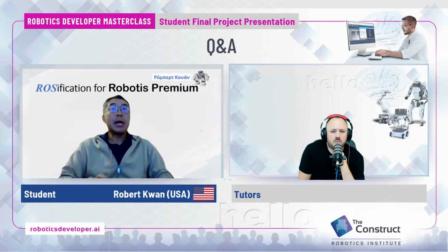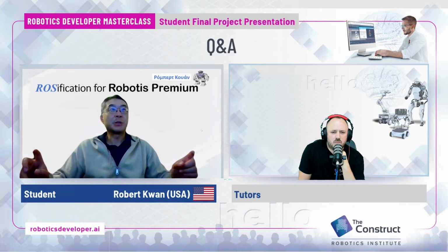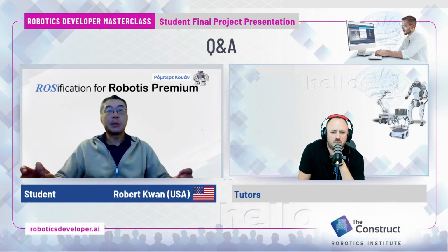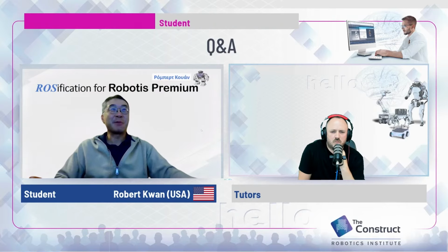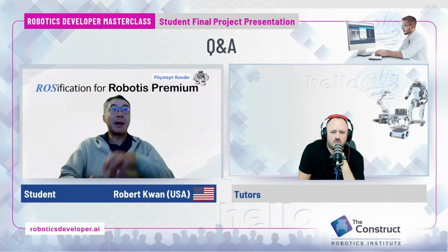At the beginning, I tried to apply that parameter value directly to their torque limit control register, but I found that it slowed down even much more than what I showed you earlier with the robot.